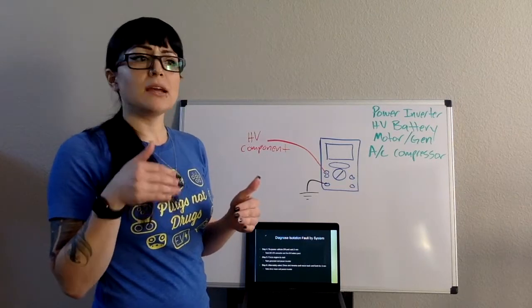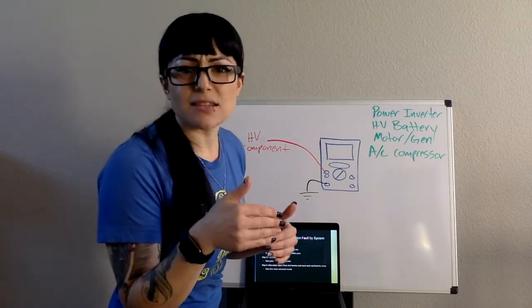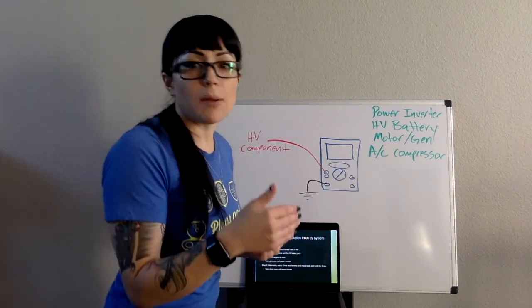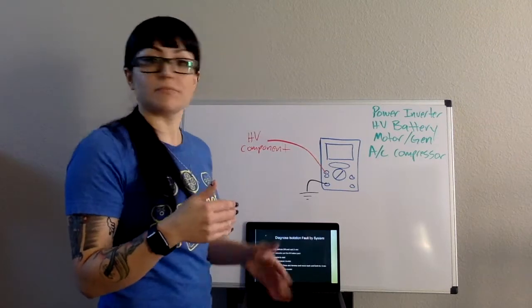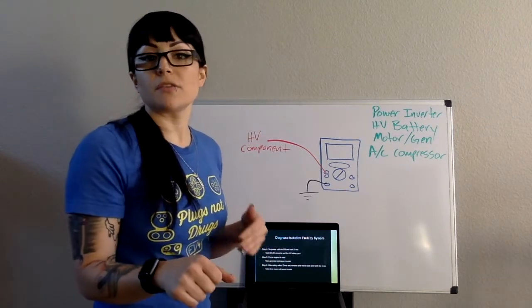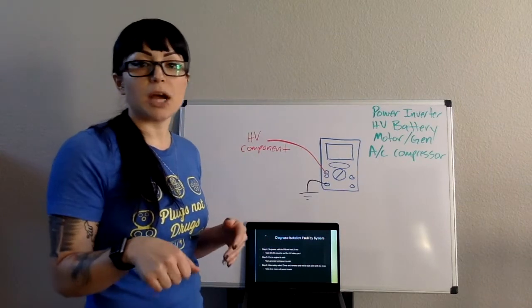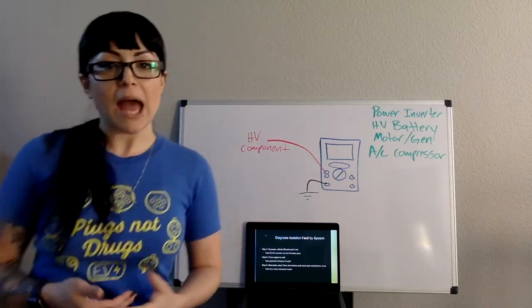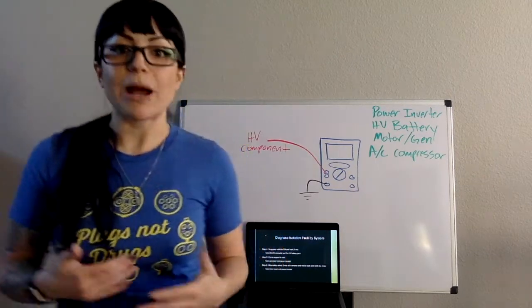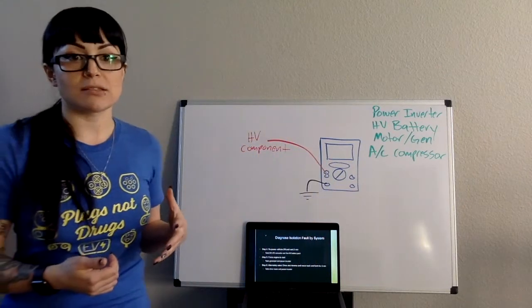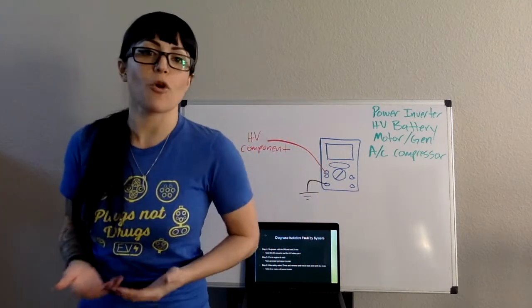If you can, you're going to want to move the vehicle at least a little bit. You don't have to actually drive the vehicle, but just move it a couple of feet. Go ahead and throw it in reverse and move it back. Throw it in drive, move it forward, throw it in reverse, move it back. We just want to get some movement happening, and we're going to want to do this for about, again, 2 minutes to try to give everything a chance to fault for us.